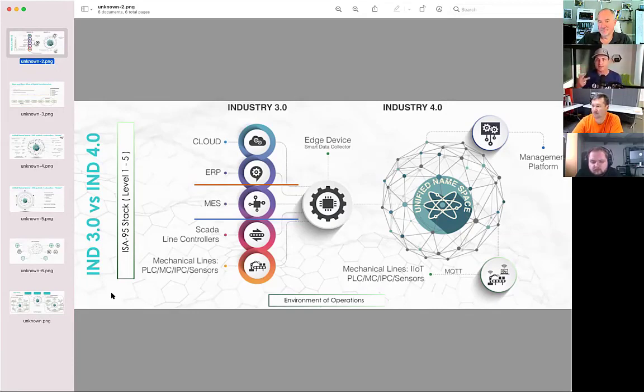You've got to be report by exception. That's the second one. Report by exception means you're only reporting data that changes, and it's reported from the edge, published into the unified namespace. Why does edge driven matter? Because if you connect everything in your network and it's not edge driven, if you're sending all of the data, you'll run into bandwidth issues, right?